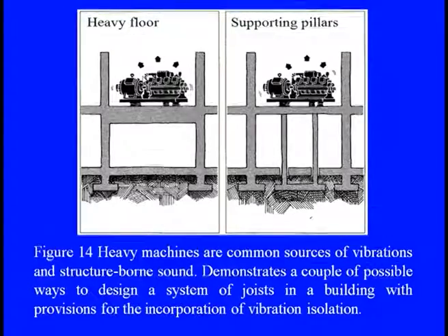But when, instead of the heavy floor, we keep a uniform floor just below the machine as the foundation, with ribs or joists in the building, the vibration isolation is quite significant, because these joists provide some kind of attached masses. Since they are concrete features, they can straightaway absorb the exciting frequencies coming down to the system.